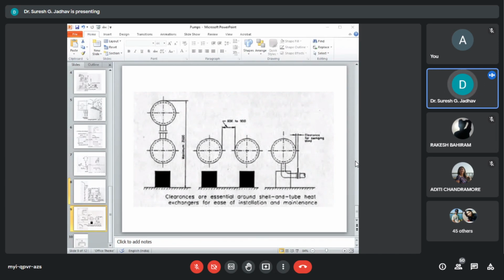Now, the next type is kettle type heat exchangers. For high evaporation rates, kettle type heat exchangers are chosen. The shell is expanded to accommodate the generated vapors. This type generally has U tube bundles. The basic principle adopted in the heat exchangers are: the working space should be kept clear of any